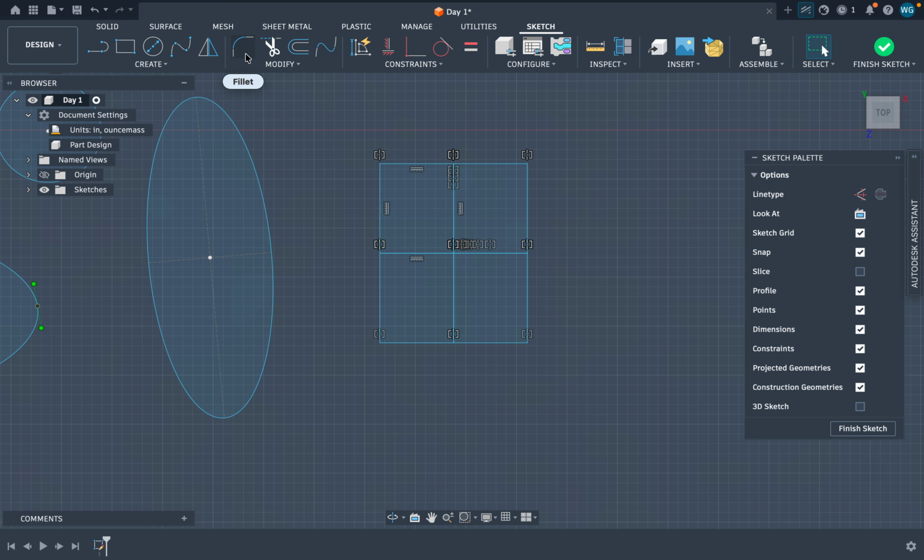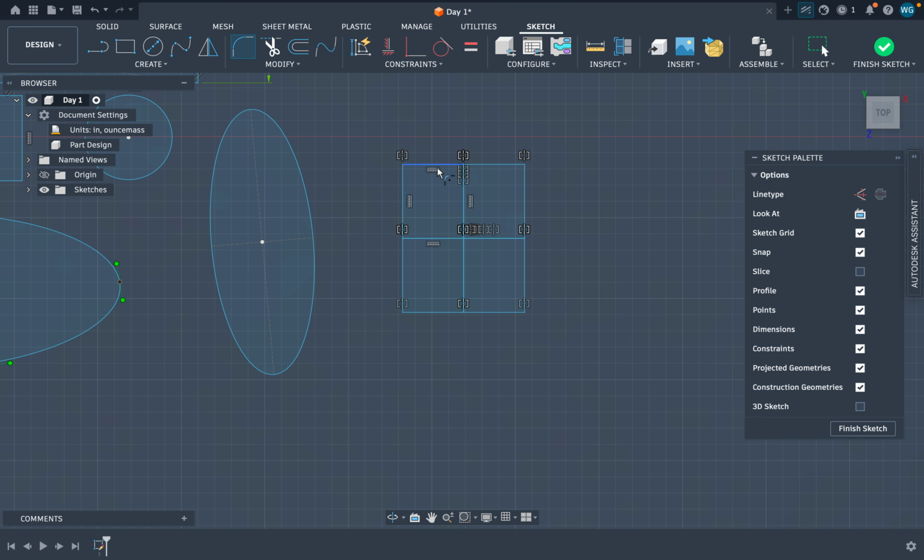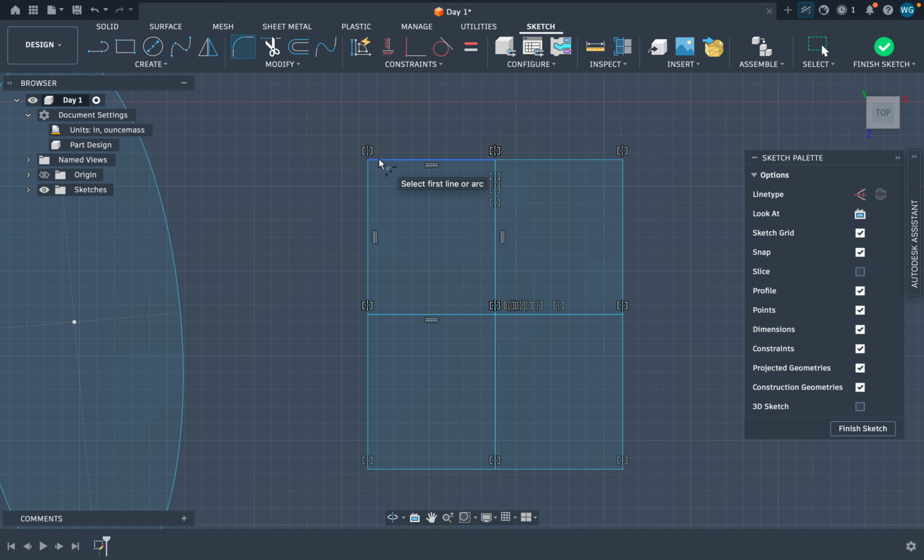For this fillet, you can use it in the corners. For example, these corners on our window, we can bend it like this. We press this line segment and this line segment, and we can move it around like this to make it curved. For example, I'm going to leave it at 1, and then I'm going to do every single corner, so they can all be 1 and they can all be equal.